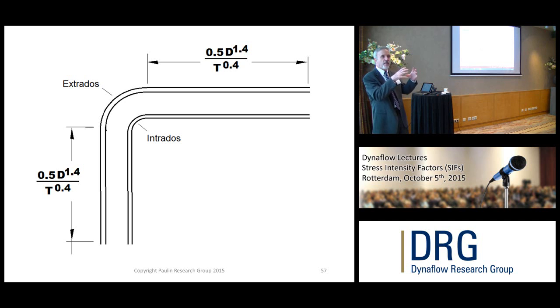If you've got a short amount of pipe, short loops, short closed loops, those are tight piping systems, and they're very, very, very sensitive to the actual values of the stiffnesses you use. A K is different now for every bend. So you turn that on, turn it off for FEA Tools, and see what effect it has on your model. That's just reality.